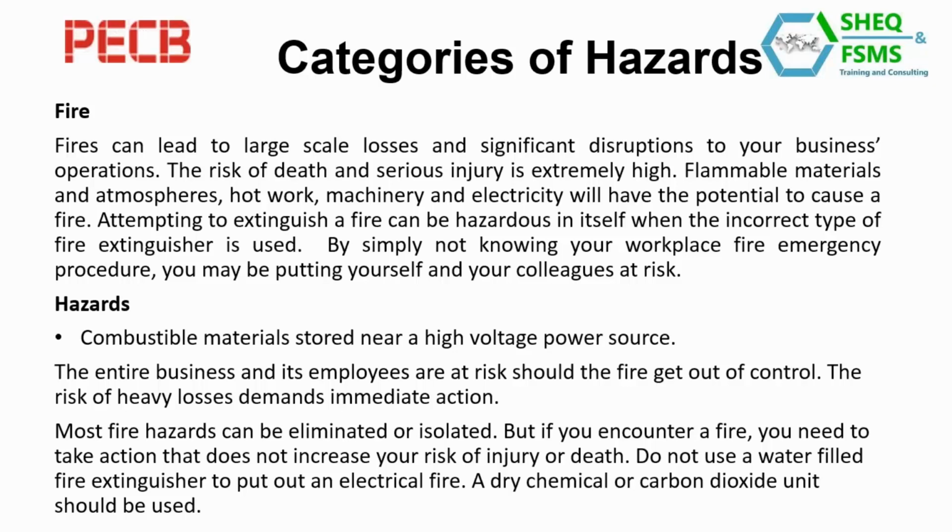And the hazards here are combustible materials stored near a high voltage source. The entire business and its employees are at risk should the fire get out of control. The risk of heavy losses demands immediate action. Most fire hazards can be eliminated or isolated, but if you encounter a fire, you need to take action that does not increase your risk of injury or death. Do not use a water-filled fire extinguisher to put out an electrical fire. A dry chemical or carbon dioxide unit should be used.